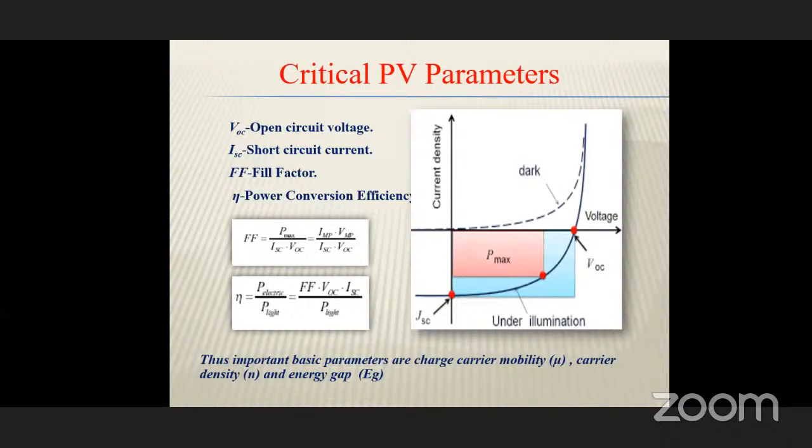The fill factor is defined as IMP times VMP over ISC times VOC, where VOC is the open circuit voltage and ISC is the short circuit current.